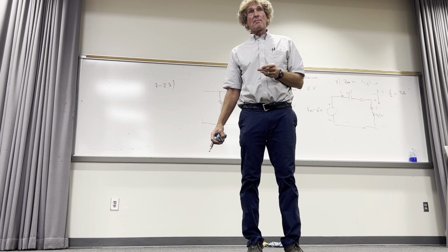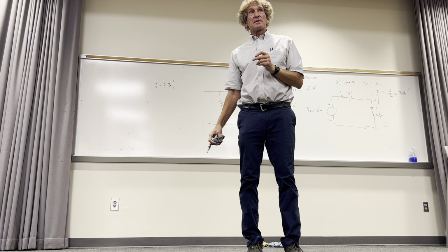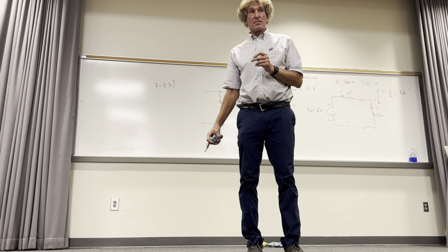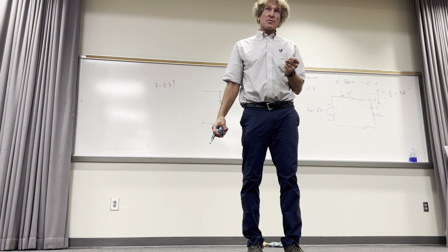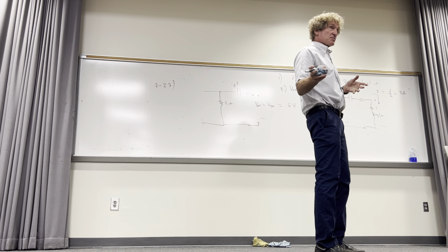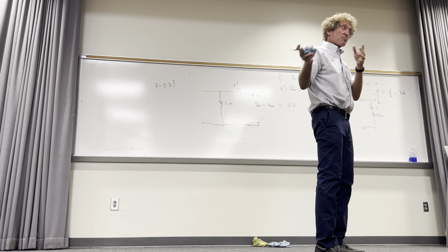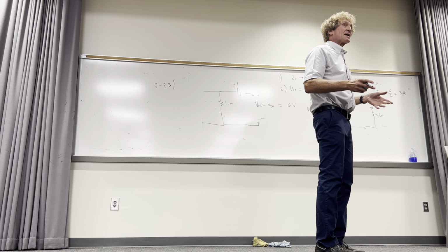That kind of a problem is a gift. The only thing you need to do is calculate the Thevenin equivalent circuit, take the Thevenin impedance and conjugate it for the load, and then calculate whatever, all right? And it's really that simple. Are we good on this one? I'll give you problems on this. This is something you work and just reinforce that idea.